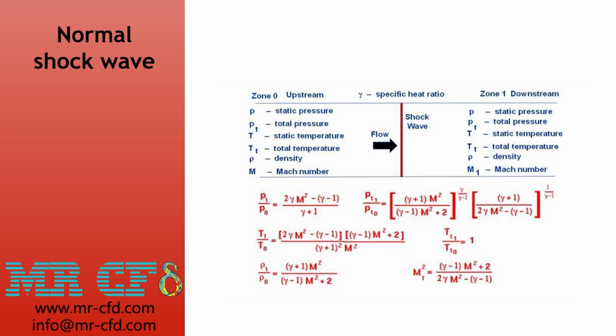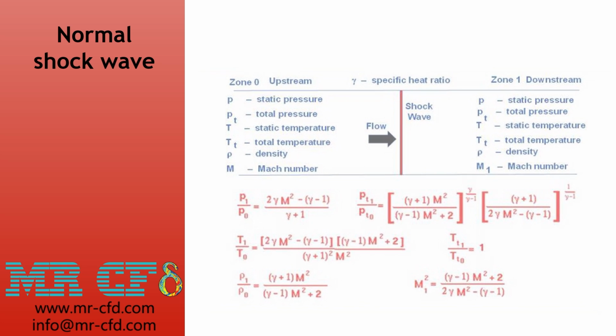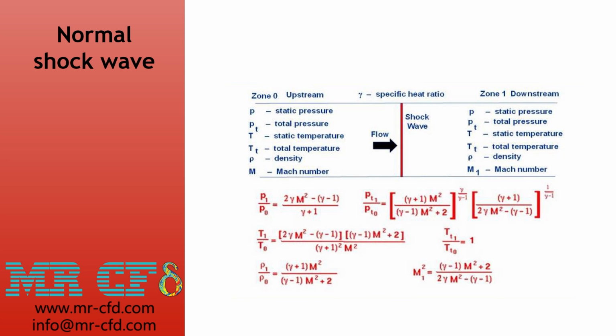Since the fluid is not flowing continuously, a control volume is established around the shock wave, with the control surfaces bounding this volume parallel to the shock wave, with one surface on the pre-shock side of the fluid medium on the left side. The two surfaces are separated by a very small depth, such that the shock itself is entirely contained between them. At such control surfaces, momentum, mass flux, and energy are constant. Within combustion, detonation can be modeled, or a vehicle passing through the air at hypersonic speed can be modeled.